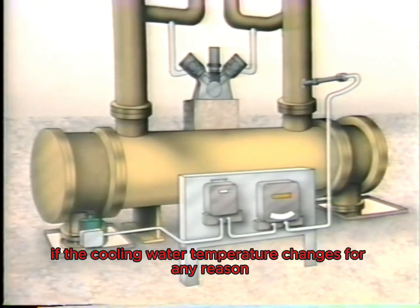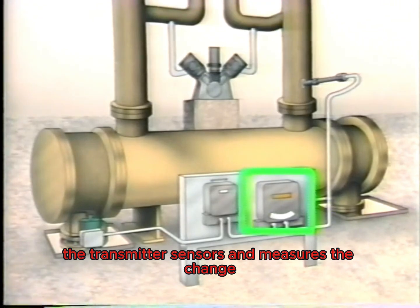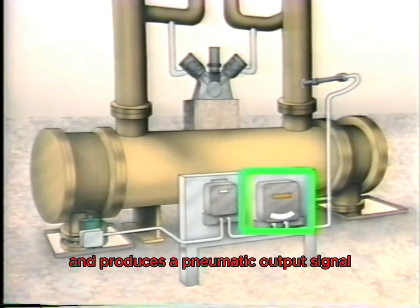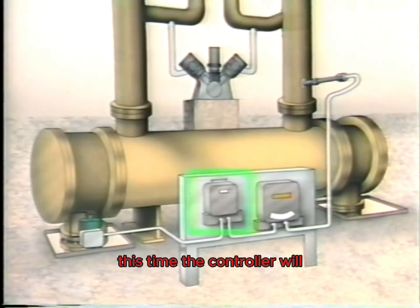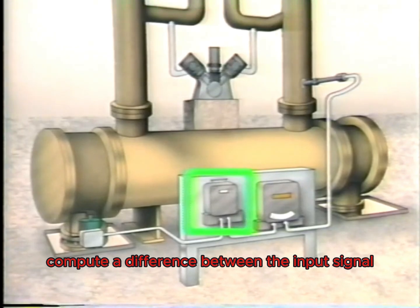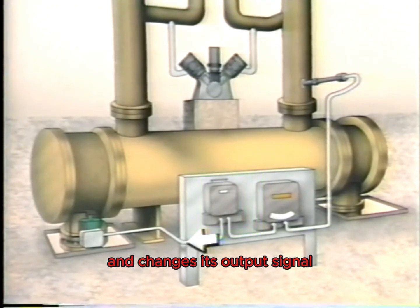However, if the cooling water temperature changes for any reason, the transmitter senses and measures the change and produces a pneumatic output signal that represents the changing temperature. This time, the controller will compute a difference between the input signal and set point and changes its output signal to represent this difference.